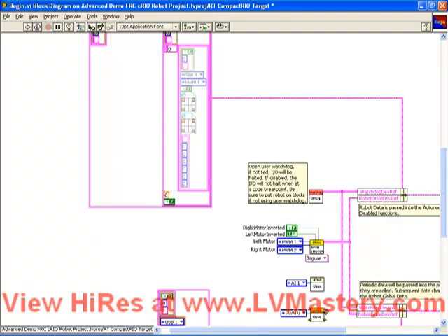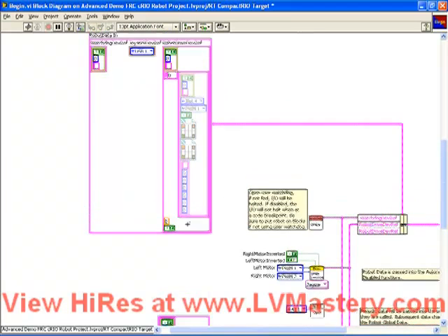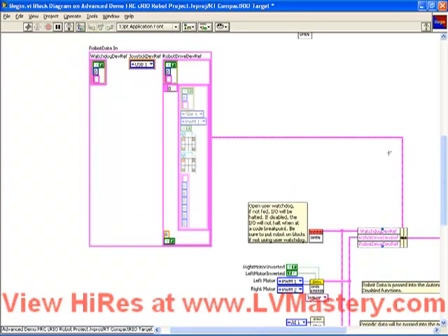So what we have to do here is actually quite similar, because if you notice, there's nowhere to wire in this gyro. If I make a little bit more room and I stretch this down, I don't have a gyro device ref here. So what I need to do is I need to create that. And remember, the definition of this data type is coming from the wire on the middle element, which is coming from this constant. So now let's take a second and talk about typedefs.